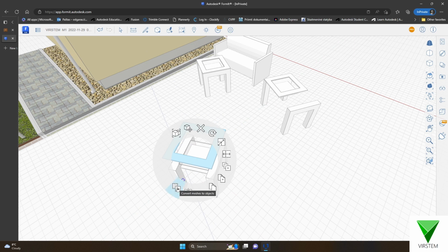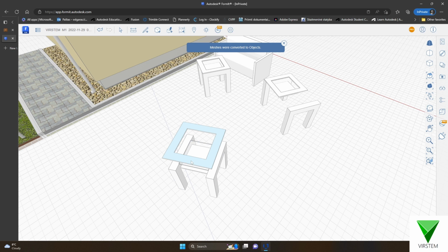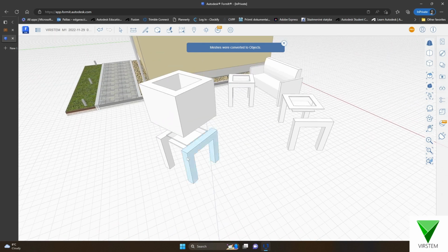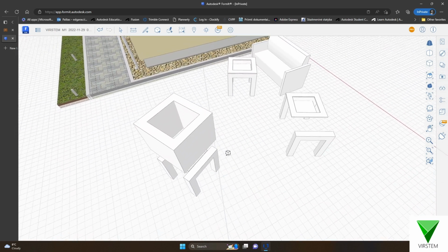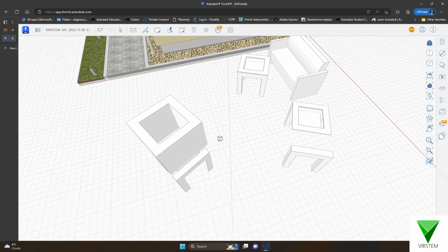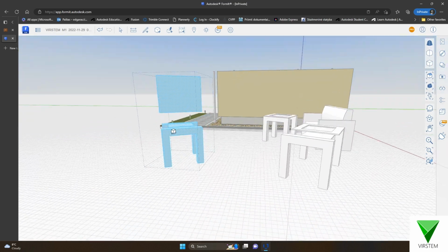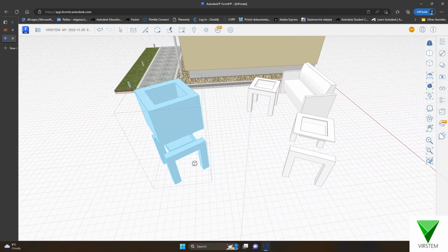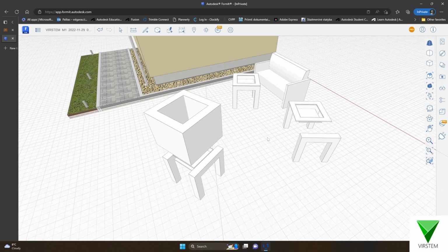And also additional context menu, I can convert this element to mesh, and I can extrude the mesh. And after you finish editing or creating a new object, always create new group. So object is in group mode always. Also, you can combine several groups in one group.